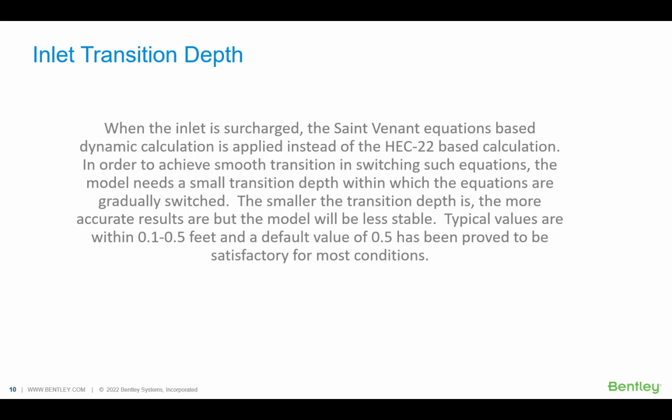The smaller this transition depth is, the more accurate your results are going to be, but the model will be less stable. Typically, values are within 0.1 to 0.5 feet, and the default value for this is going to be 0.5 feet, which has proved to be satisfactory for most conditions.